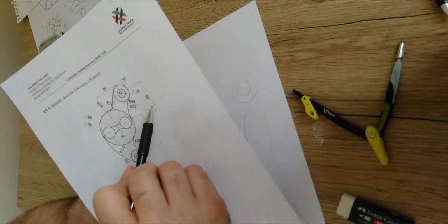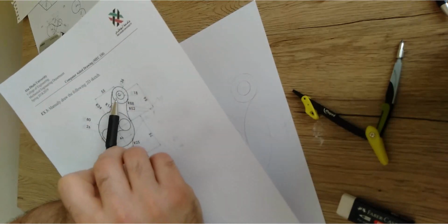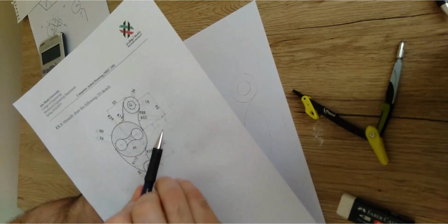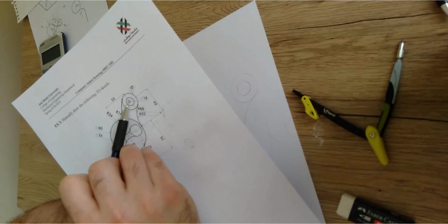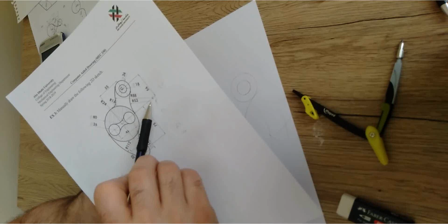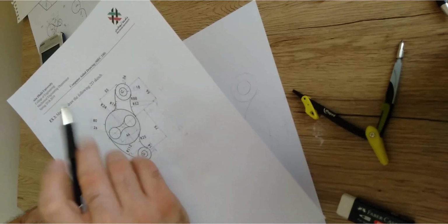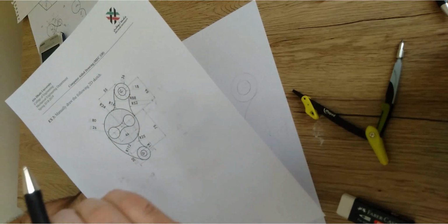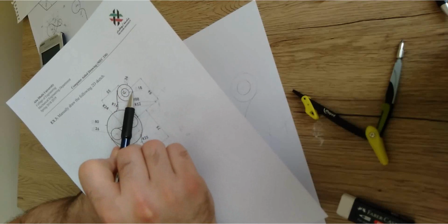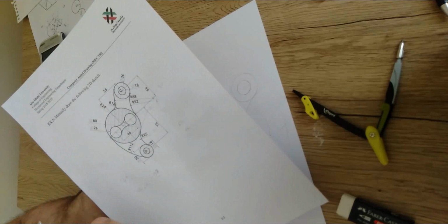Then from this center, I'm going to draw a curve. This curve should have a radius of R88 or the subtraction, it depends. Why? Because if this is the center of the curve R88, and you try to move to the center of the circle, why are we moving to this one? Because it is tangent to the R88 curve. If you try to move from center to center, are you going to go over this tangent point of the R88? No. So what does it mean? It means that we have to subtract. We're going to subtract R88 minus 18, which is the radius of the big circle. So in total, it's going to give us 70, right?